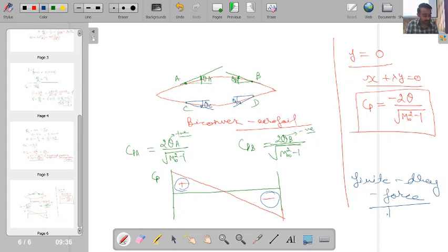And this particular drag force which is coming on this body is called the wave drag. We know that in case of subsonic flow there is no shock wave, but in case of supersonic flow a shock wave comes, the shock wave alters the flow field and ultimately it causes a positive drag, which is called wave drag. So though in our linearized theory we have nowhere talked about the shock wave, ultimately whatever value of Cp we are getting is giving us the finite drag, which is called the wave drag.